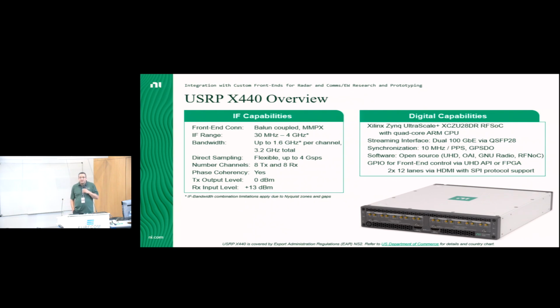The X440 is a newer device that we introduced last year. It is a baseband-based device. Both devices use the Xilinx RFSoC chip. This device provides 1.6 gig of bandwidth per channel across 8 channels, but that is at baseband. There's no tuner or RF front end on this device.